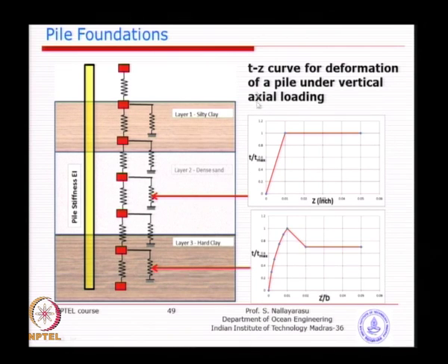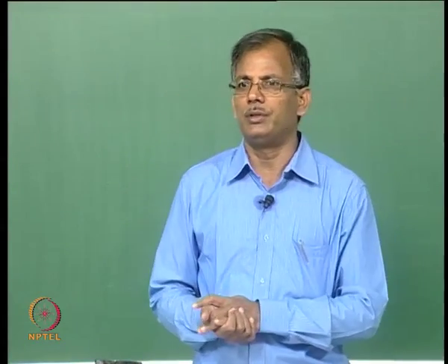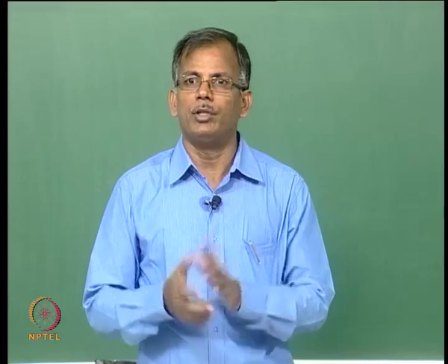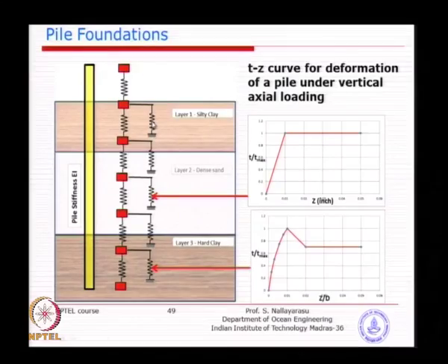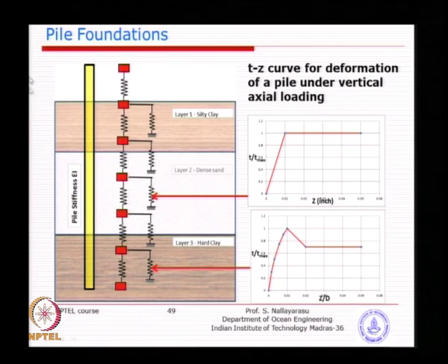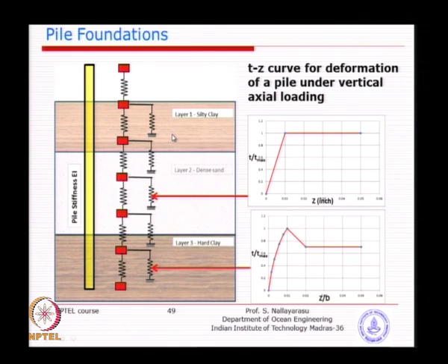So, ultimately why do we need this when you are doing a system analysis? For example, you want to study the jacket overall behavior of load displacement, you need to describe soil as a spring and transfer the springs into an analysis, because after all every structural element is a spring element. It could be an axial spring or it could be a bending spring or it could be a torsional spring. So, similar idea, you translate the soil material as an elastic or inelastic material with a spring value, whether it is linear or non-linear. Once you do a characterization like this, this becomes part of a structural analysis. So, you do not need to worry about the soil as a separate material that you need to divide and then analyze.